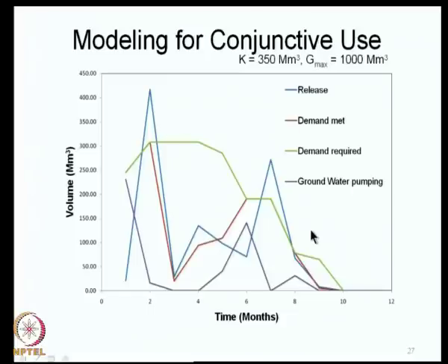Now, on this you can do several sensitivity analyses to see how sensitive the solution is to the reservoir capacity K. You try increasing the reservoir capacity K, but you will very soon realize that this solution may become insensitive to reservoir capacity itself, because it may be limited by the inflows.